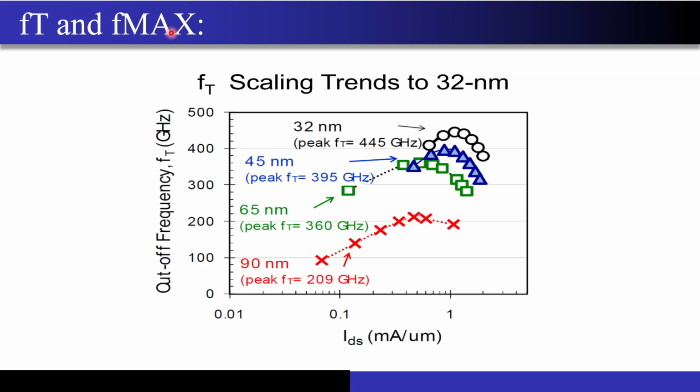So now the higher bandwidth you cannot get at a very low frequency. If I tell you to design an amplifier which can give me a bandwidth of 2 gigahertz at a center frequency of 3 gigahertz, it's extremely difficult, very, very difficult. But if you tell me to get the same 2 gigahertz of bandwidth at around 30 or 28 gigahertz, it is easily possible, correct? So higher the bandwidth you want, higher the center frequency you choose, because this is the concept of the fractional bandwidth, that you may study or you may already be knowing.